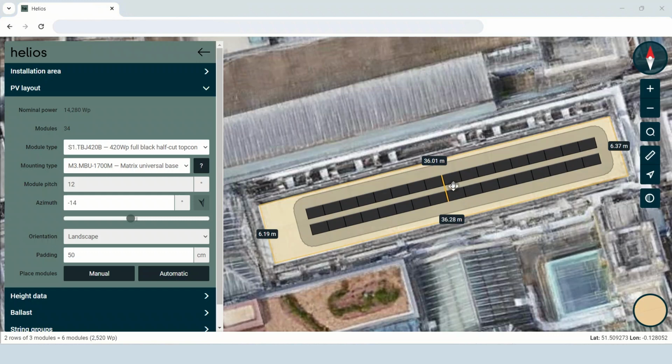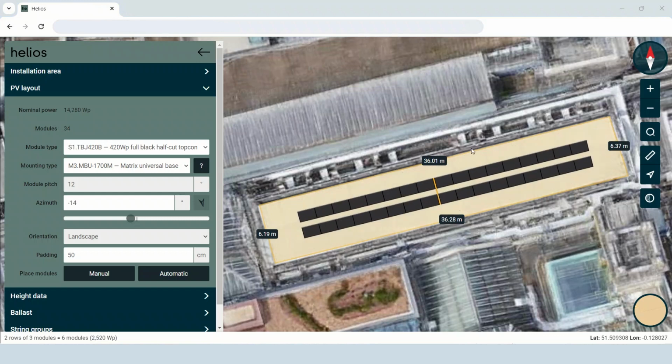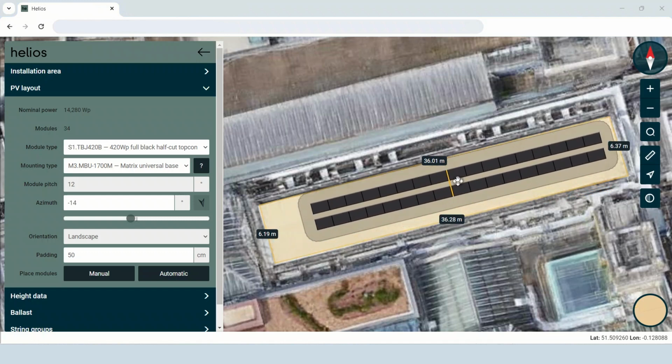Once you have created a field of panels, there are several options to customize the design. Selecting multiple panels in the field is done by holding down the right mouse button and dragging. Undo the panel selection by pressing Escape. Press the Move icon on your screen to move the entire field. Click on a panel to select it.